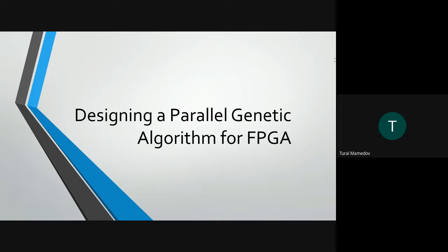In implementing neural networks on FPGA, each network layer works in parallel with others, which allows using the pipeline principle. And neurons in each layer work in parallel too, according to the principle of multiprocessor processing of data. And thus, every neuron is a separate process, and processing information in each neuron is carried out simultaneously.